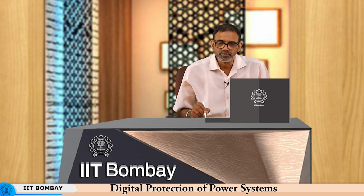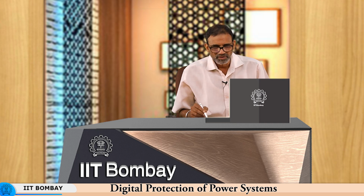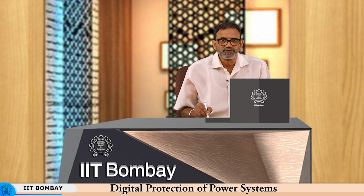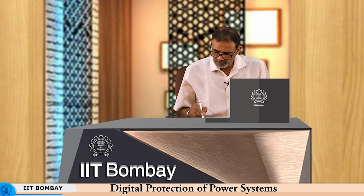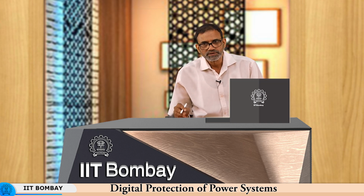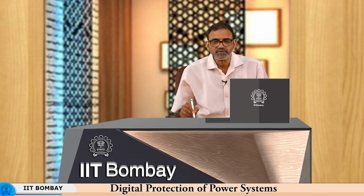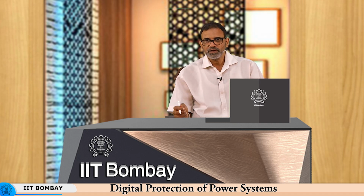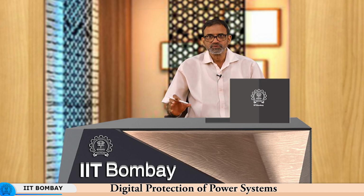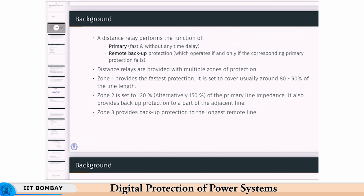So, you generally limit it to 80 to 85% of the line length. Then zone 2, depending on the adjacent line, if it is too small or of reasonable length, is set to either 120% or 150% of the primary line impedance. Its primary aim is to provide backup protection for the remaining 15% or 20% of its primary line and also the adjacent line. Okay, because you can't leave that 15% unprotected. So, you have to provide a slower protection there.